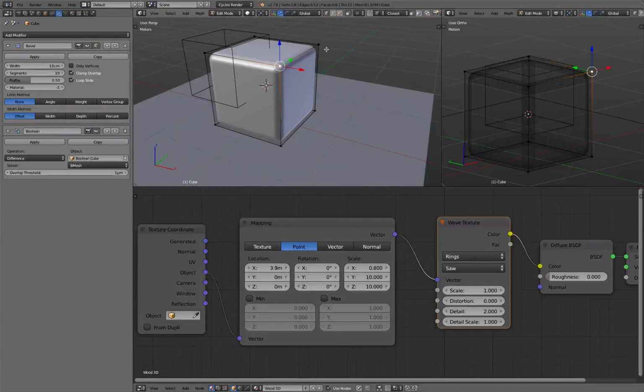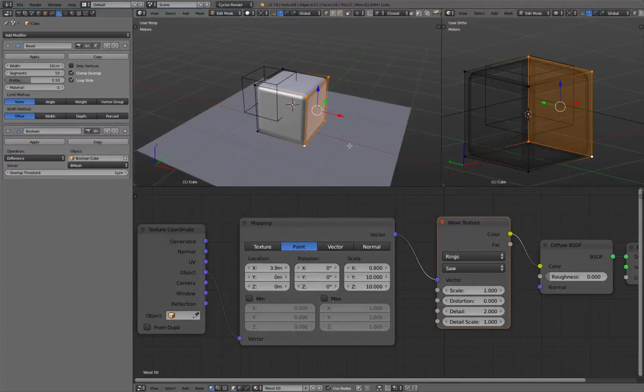With the shift button pressed and then left mouse button click, I can select all these points. During class, I saw that people were trying to move these points, and then later, instead of having a cube, they ended up with other interesting looking geometrical shapes. That's pretty common when you're a beginner. So there's a little bit of modeling discipline you have to learn.